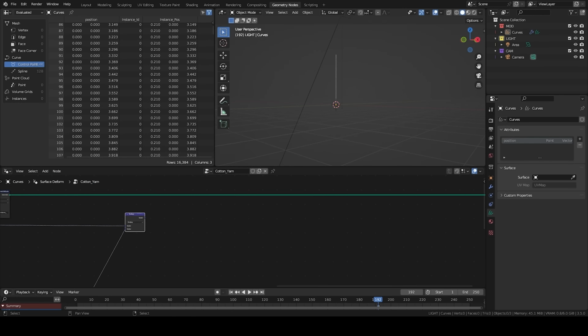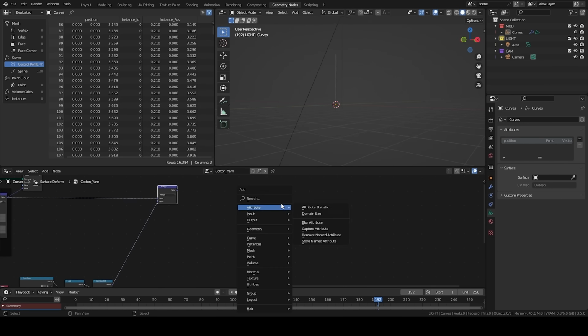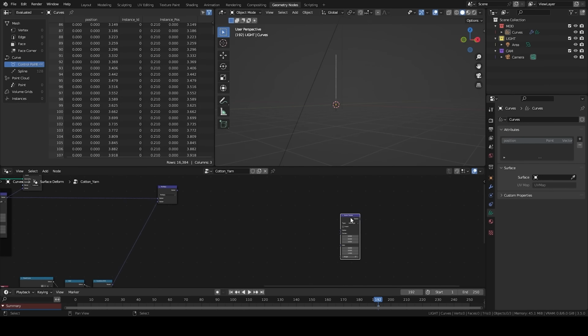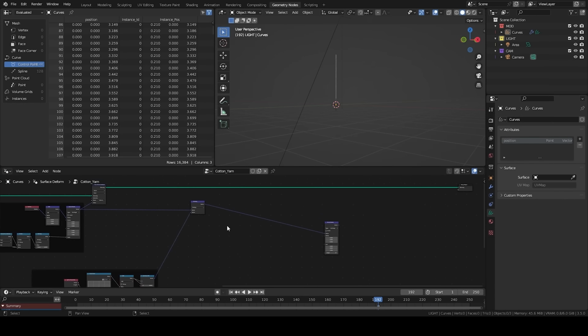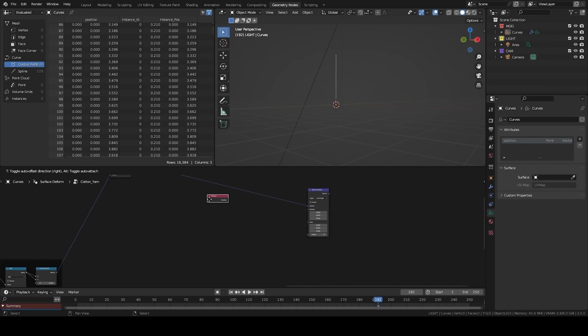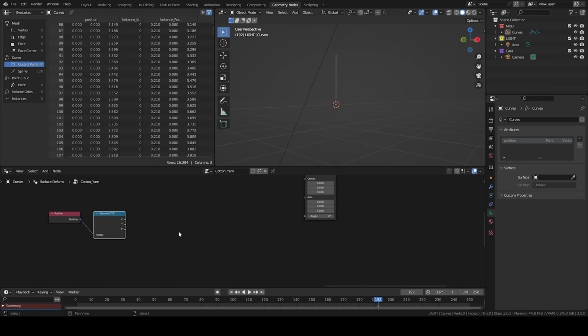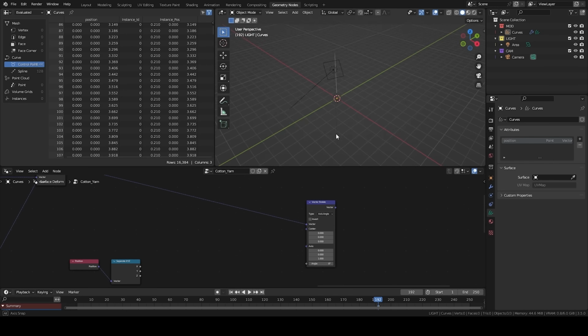We can move on. I'm going to create a node that's called vector rotate. We've already stored it. I'll put the changed positions in the first entry. I create a little backdrop around it to have a little more clarity. I make a position node. I separate X, Y, Z. I'm only retrieving the Z coordinates, and that's going to allow me to build this kind of spiral.